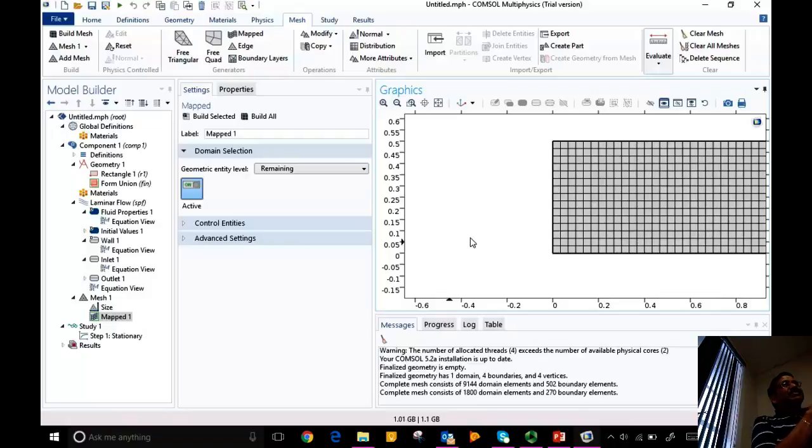I'm solving Navier-Stokes equation. There is a wall, so there must be a boundary layer near the wall, right? But that may not be true if viscosity is very high. The boundary layer thickness may be so large, I don't need to resolve that. And we will do the simulation for 2 different viscosities, and you will see what happens to the boundary layer. But having a fine mesh in a region where gradients are not large, you're doing unnecessary additional work, but it is not going to lead to an error.